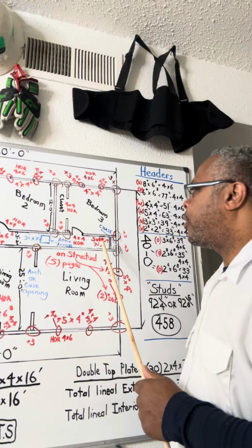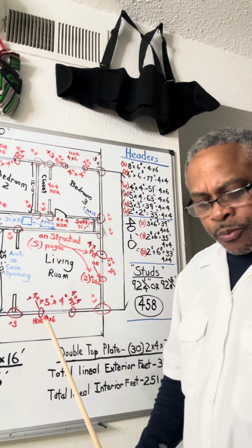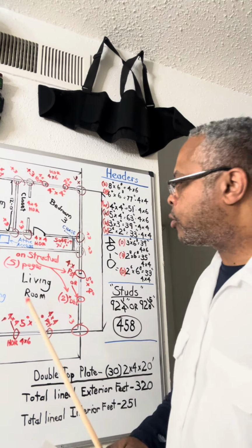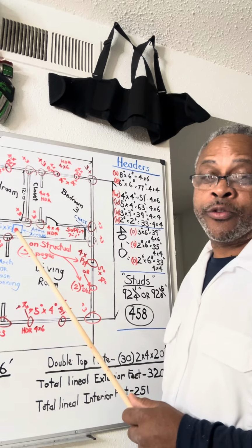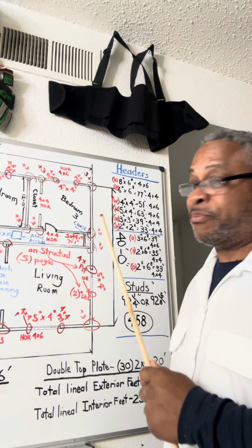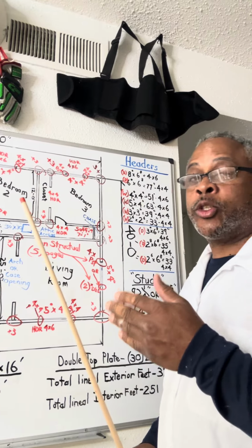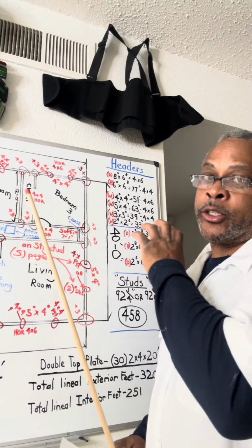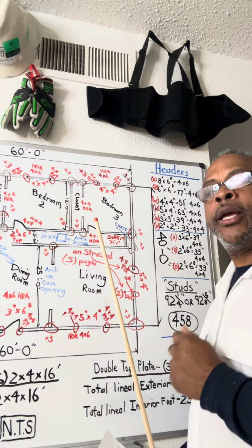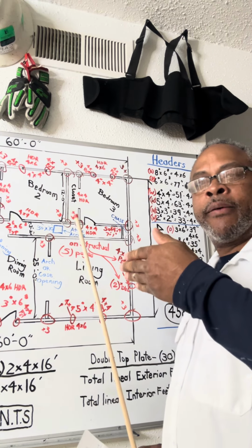A lot of your soffit material, like I had soffit material, and I had 12 studs for soffit. I have 12 2x4s for soffit, because with your 2x4s and your plate material, you're going to need a ledger on that wall so that your 2x4s can run on both sides of the wall into a ledger. What is a ledger? It's a flat 2x4 that runs alongside the long length of that wall for that hallway, and it's going to nail to a finger joist. We call it a finger joist, and it's actually a soffit 2x4 on edge.